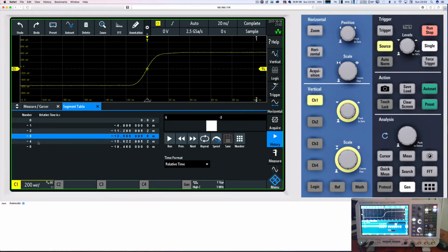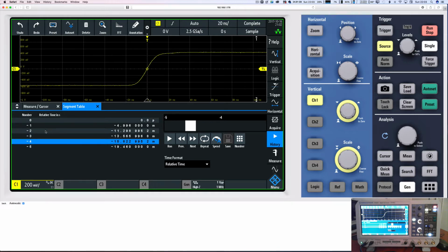They look identical. You can just see some change on the waveform, but it's so minor. This would be particularly relevant if you were trying to capture digital signals, because you set your trigger up and you could then set up 30, 50, whatever, depending upon your memory length, for the actual signal, so you could capture them. So the history function, which is an option on the scope, is a very powerful option.